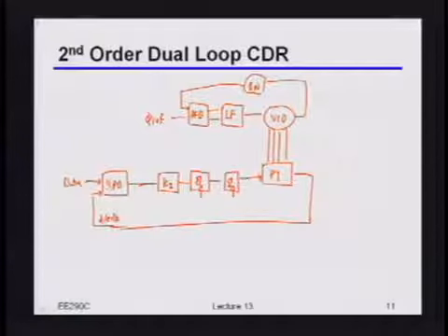Okay, so if I'm really building the equivalent of a PLL, will what I just drew here work, or will this have a problem? Yeah, it's unstable, right? I just put two integrations in the loop with no stabilization, no zero, nothing. So how do I add the zero in?